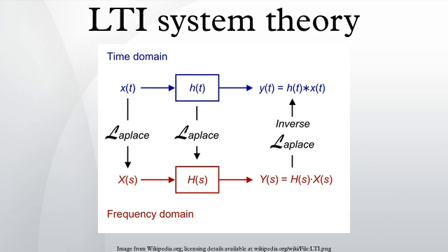The weighting function is h[k], simply shifted by amount n. As n changes, the weighting function emphasizes different parts of the input function. Equivalently, the system's response to an impulse at n equals 0 is a time-reversed copy of the unshifted weighting function. When h[k] is 0 for all negative k, the system is said to be causal.